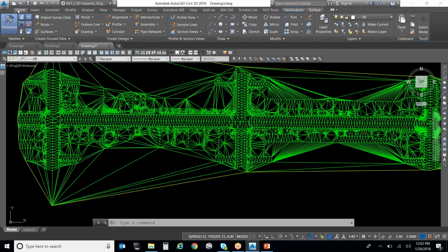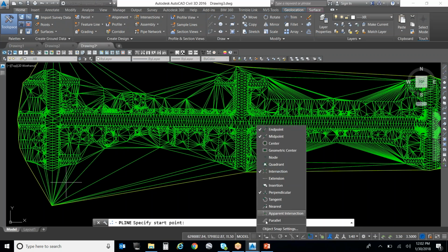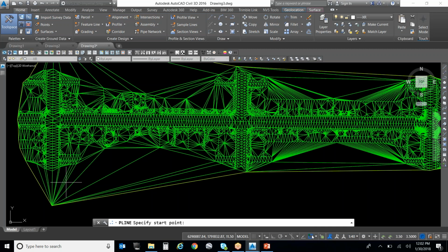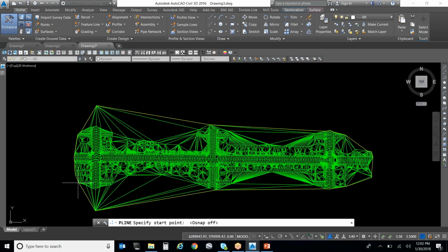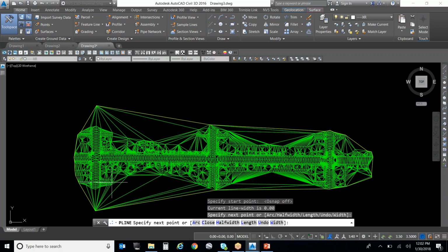You just go ahead and add a polyline. And I've got to make sure that I'm not picking points, because that's... See, sometimes it's quite useful, just to look at it in 3D, to get a better impression of what's actually... Let me draw the boundary real quick, and then I would do that. I definitely recommend looking at the 3D orbit of any surface you create. Yeah. One caveat, make sure you save first.